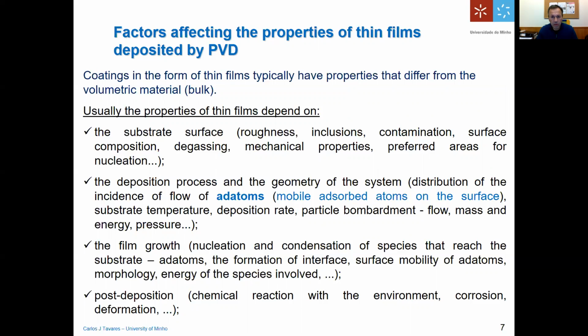And you also have to take into account some preferred areas of deposition, which will actually be initiated by small clusters in nucleation, which means that, for example, if you have your substrate, which has lots of defects inside, then these defects, like pinholes, discontinuities in your substrate, they will be active centers for the atoms that reach the substrate to start to grow there. And so these aspects will actually influence the final form of the film.